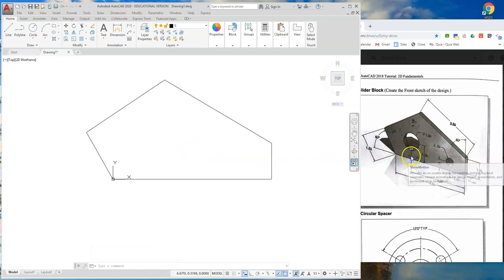So because I started this point at 0,0, it's going to be a little harder to do the X and Y coordinates for the holes. So this time I'm going to just draw some reference lines, and if I use reference lines to lay out the circles, I need to make sure that I go back and erase those at the end. But I'm going to go ahead and lay this one out. This one is 1 inch from the corner, and it's 1/2 inch up. And remember that symbol right there means that is a diameter of 0.5.